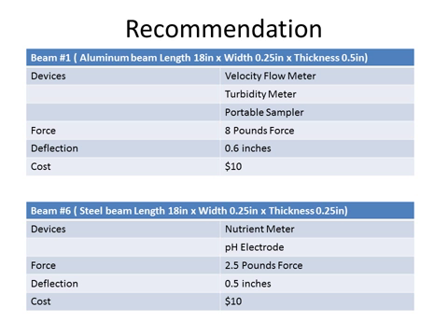We chose these 2 beams because they are the 2 cheapest, but it does bear mentioning that there was the $4 beam, which was significantly cheaper. However, with the force we calculated, it would not handle the load of any of these devices. So effectively, we chose the 2 cheapest beams that would support the drag weight that we needed to support.